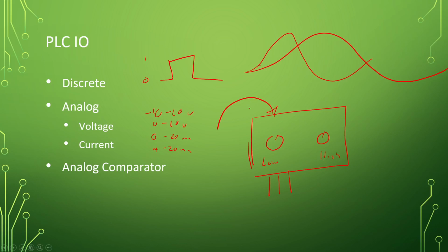So that analog signal comes in, and you have a part there, and you say anything that's less than this magical dial position is too short. Anything greater than this one is too tall. So anything between those is an acceptable height. And then on the bottom, we have a low, acceptable, and a high signal. So all you have to do to tune that is you just twist the little dials and you're good to go.